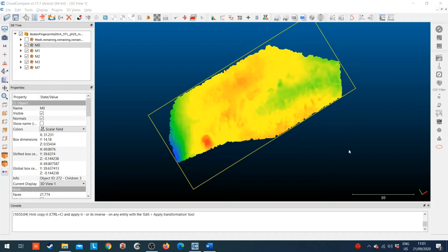As briefly explained at the start of exercise 3, some of the functions of CloudCompare work with the vertices of the mesh as a point cloud rather than working with the mesh itself. This is the case for calculating roughness, surface variation, and other morphometric parameters that you'll see here. These individual points are the only real data anyway, as they are the points that were measured during data capture, no matter which kind of data capture it was. The mesh is actually a rough approximation of the object surface based on the density of your point cloud. So making these calculations off of the point cloud is technically more accurate anyway.